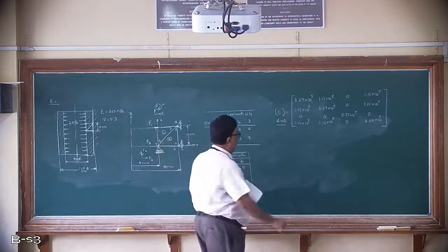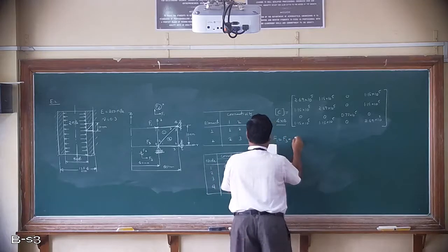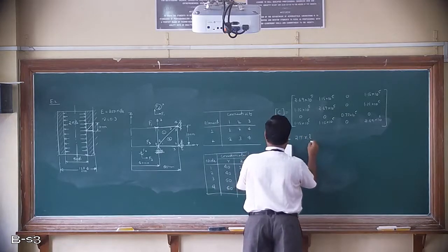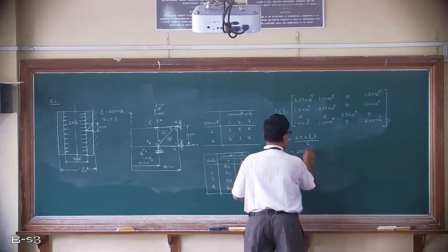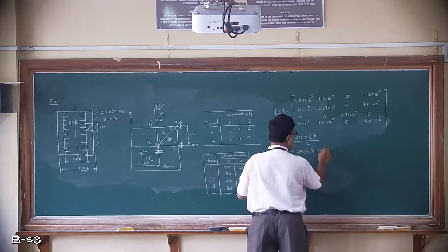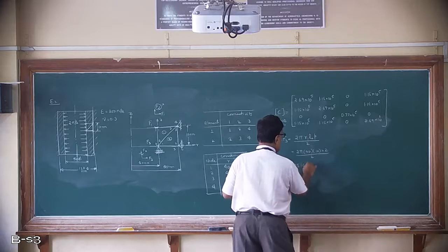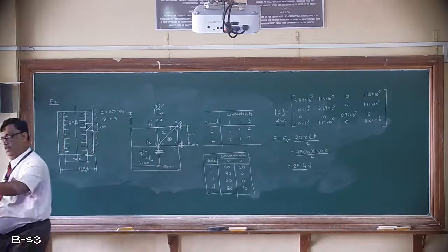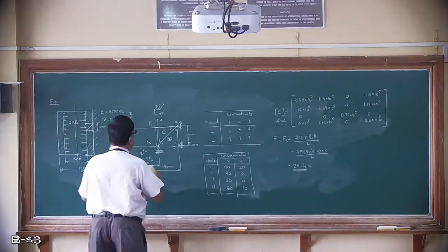Then these forces, F1 and F3, are going to be equal and can be found out by 2 pi R1, length of the element into the pressure, divided by 2. So obviously 2 pi, inner radius is 40, length of the element is 10, pressure is 2 megapascal, divided by 2. This comes out to be 2514 Newton on both the nodes. The force is going to be equal on both, so we will consider these as the two forces.